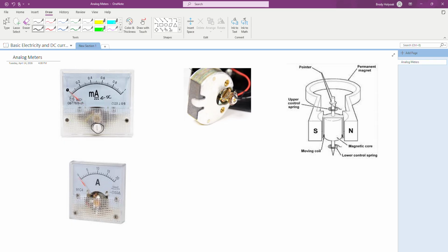Then you're going to run a current in through this floating electromagnet. And an electromagnet at this point is just a big coil of wire. It's wire that has just been wrapped and wrapped and wrapped, and it sits around a shaft like that. So you're going to run a DC current into this wire. You've got your positive connection here, you've got your negative connection, and that's going to run out to whatever it is you're hooking it up to.